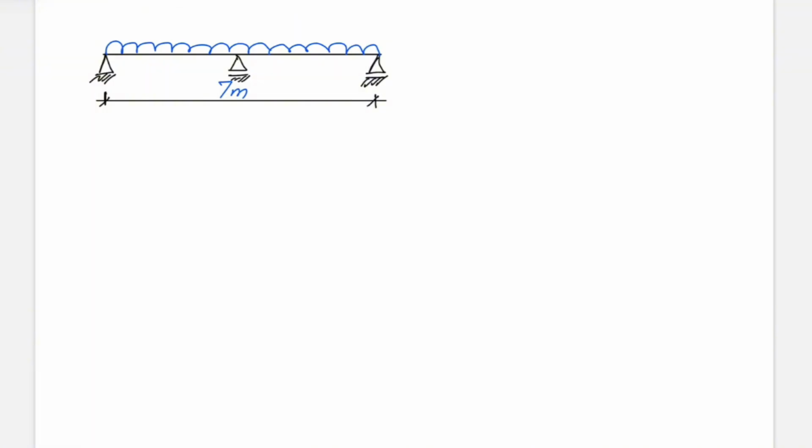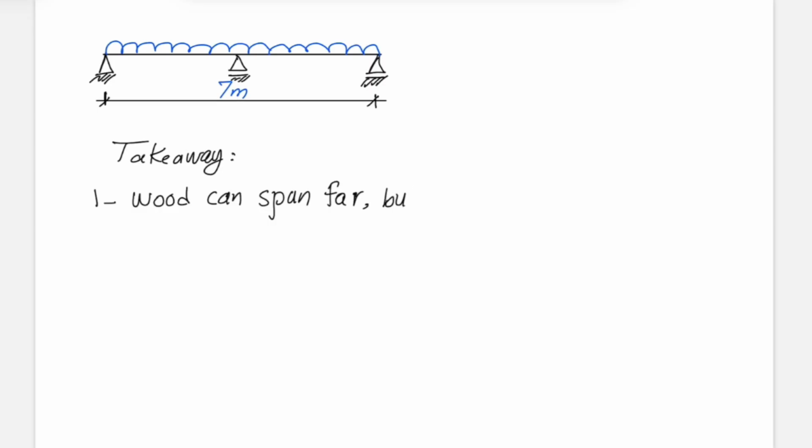One final point. Passing the deflection limit does not guarantee a comfortable floor. For long spans, vibration and natural frequency can still govern, and more advanced analysis may be required. So the takeaway is, number 1, wood can span far, but not always practically.